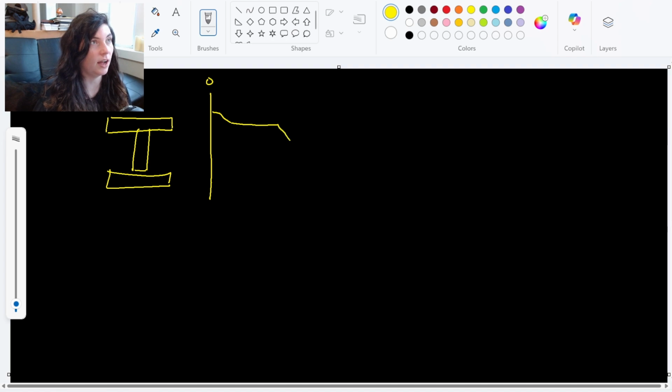And now we've got a high shear stress till we hit the centroid. So the center of our beam is somewhere in there. High, and then it comes back down. It gets lower and lower till we hit that cross-section change again. Shoots back down, and then there's just a little bit until we get back to zero shear stress.